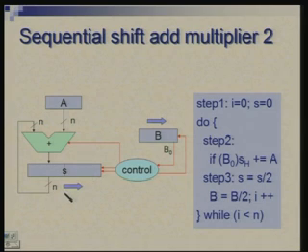So there is one more subtle point here, is that when you are shifting S right, there is a carry which might come out of this, that has to enter. So it is not a pure simple right shift with 0 getting stuffed into the vacant position. It is this carry which you do not want to lose. It is an intermediate carry which has to be accommodated here. So apart from that subtle consideration, it is very straightforward. What we have achieved is, we have reduced the size of this register by a factor of 2, we have reduced the size of adder by a factor of 2.